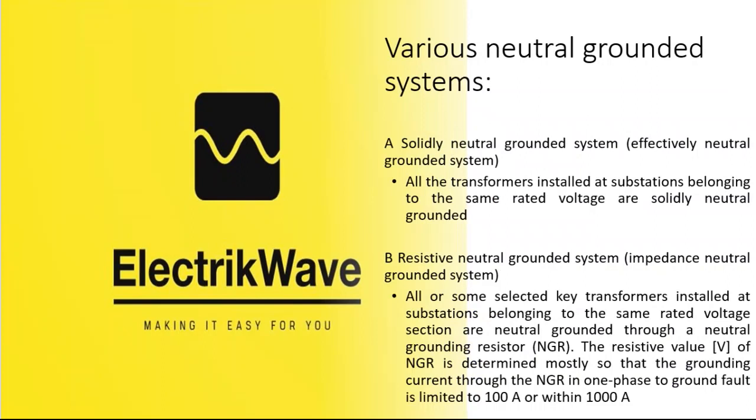Various neutral grounded systems. A. Solidly neutral grounded system or effectively neutral grounded system. All the transformers installed at substations belonging to the same rated voltage are solidly neutral grounded. B. Resistive neutral grounded system or impedance neutral grounded system.